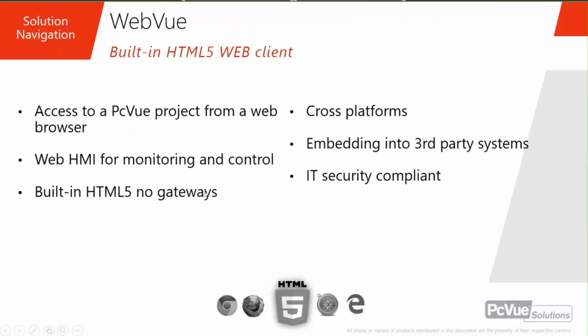The second way to remotely access with a remote HMI is a built-in HTML5 web client that we developed, and it's called WebView. With WebView, basically you can access your PCView project from any web browser. So no need to install anything on the client side, obviously, and from any web browser you can then monitor and control your process.